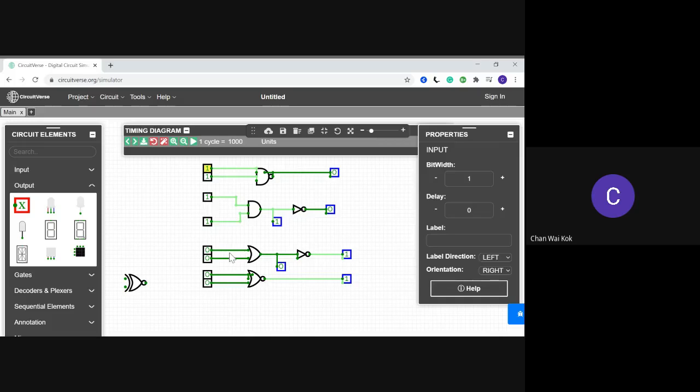All right. So this is an OR gate. So 0, 0 is 0. When you put it in an inverter, it is 1. So you can see 0, 0 is 1. So basically, this NOR gate is actually this bubble you push all the way in front here. So this is a NOR gate. Okay. So if you put 1, this one will become 0. So both of these are equivalent. Equivalent circuit. Okay. Clear.